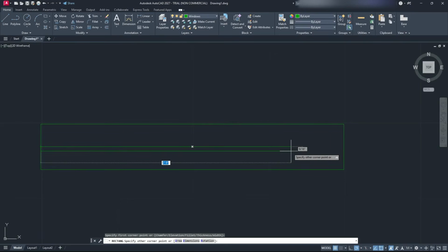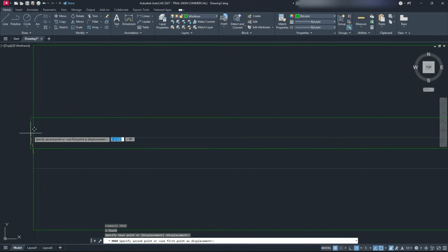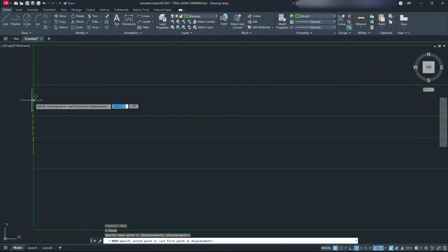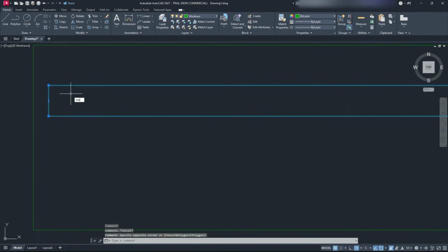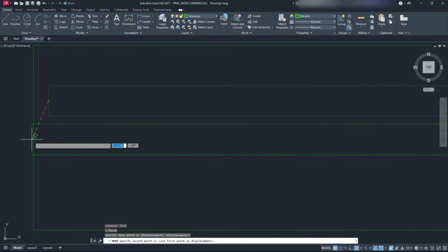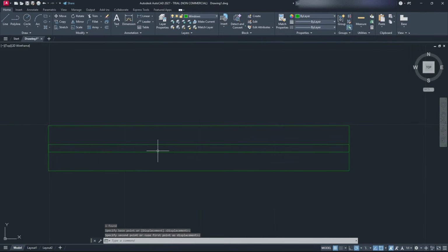So we're just going to go across by 40, make it 40 inches and then we're going to make that 1 inch. And there we go. And then what we do is we take this, we move it again, we grab the center point, and then we find the center point of this one right here. We can see the center point's right there. So we just grab this again, we move it, we can take the center there, put it right there, and then it's going to be put like that. And we have something that kind of more resembles a window. And then we can add an awning if we want to.